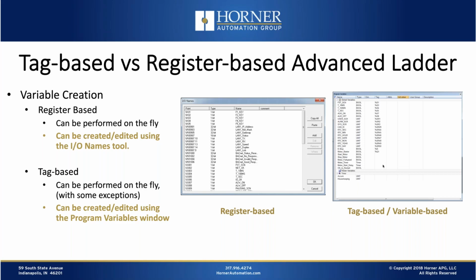And also in register-based logic, you have the IO names dialog that's used for editing, adding, deleting, copying, pasting. That's a tool that can be used to manage your variables when you're not creating them on the fly.